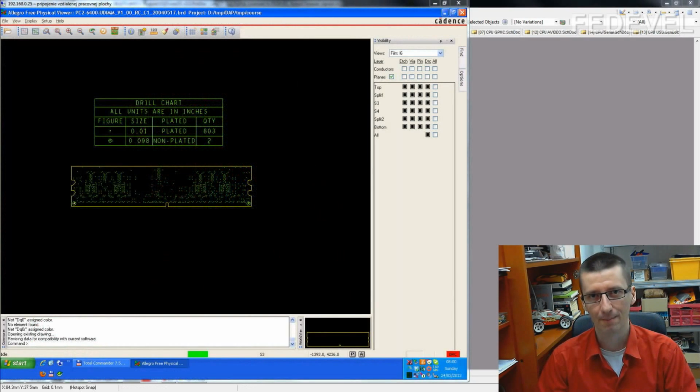Before we move to the next mystery point, we are going to have a break, and yes, bonus time. Today I'm going to show you how big a difference there is in the layout between different memory chips, and you will see the connection stays the same, the schematic is the same or very similar, but you will see how big the difference is in the layout. That's the point why it's always very important to read design guides.